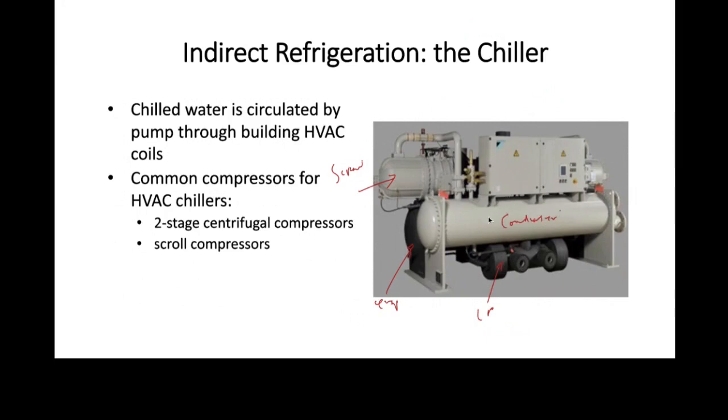The whole idea is to give off heat. From this compressor, we've got a discharge line that discharges the gas into the condenser. We've got CW in and out connections. And somewhere there will be chilled water connections. They don't show up on that picture.